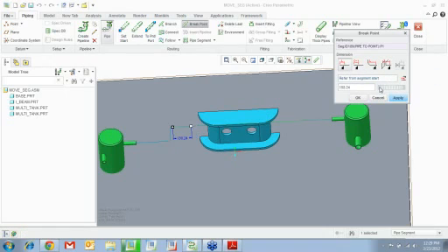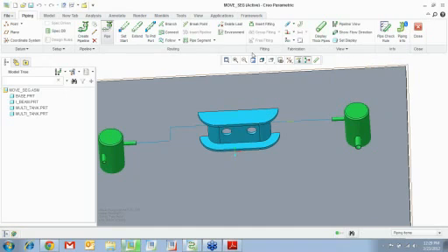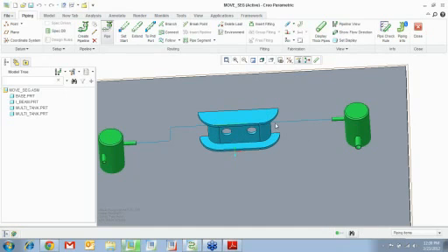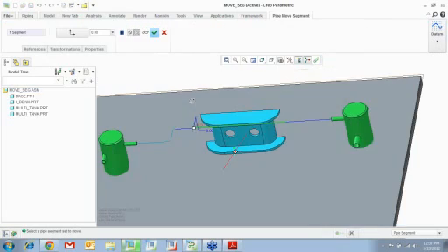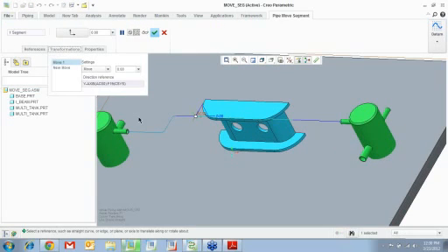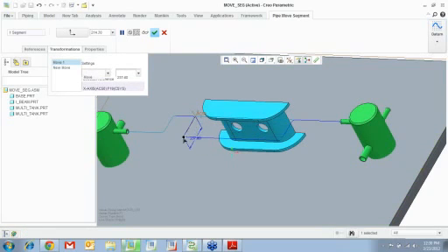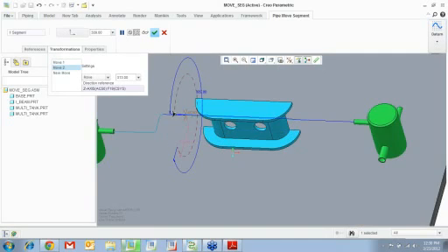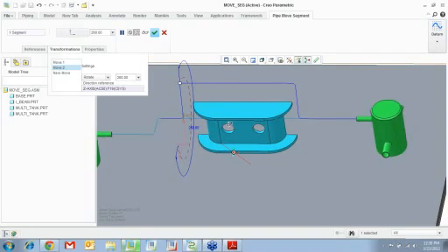Okay, so you can move it however you want. Say OK. Then insert another break. Say on this side. OK. Now you can select that pipe and say move. Now when you move, you see this is very similar to your copy paste fashion. Okay, move in the X direction, you can drag it, see that? Then you can say new move, I want to rotate, and rotate with respect to Z, and you can rotate it.